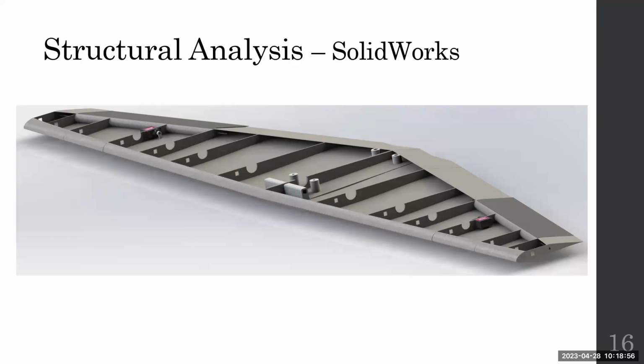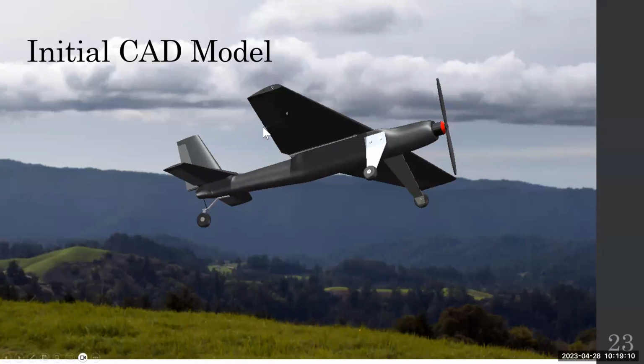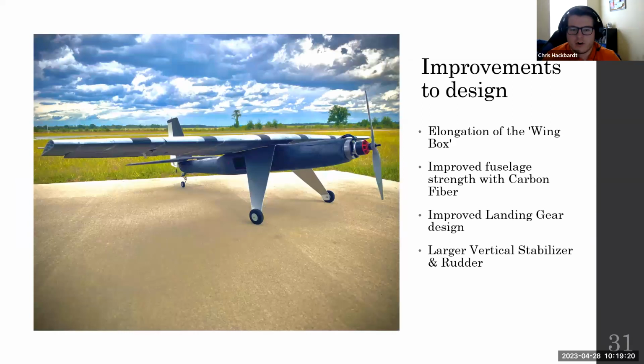Okay, and I see your servos' arms are coming out the bottom of the wing. Was that intentional? Yes. Okay, why is that? Want me to explain? For any modifications to the airfoil, we wanted all the changes to be on the bottom of the airfoil, because the top of the airfoil is the most important part to be as smooth as possible.